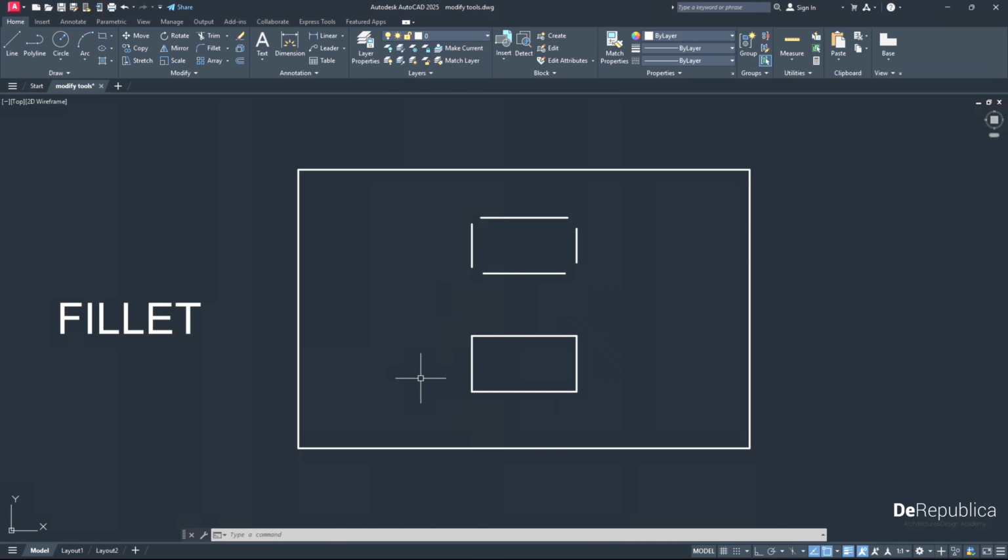Now, we have a couple of commands left, the fillet command. I have this shape here, and as you see, the lines are not connected. To fix this, activate the fillet command, click radius and type 0, enter, and now specify the lines which we want to fillet.